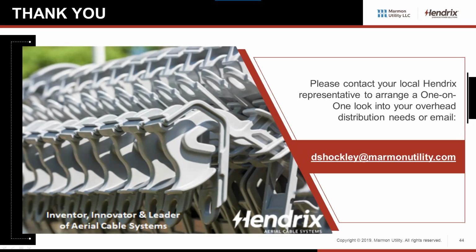Obviously a good chunk of our spacer cable is used in heavily treed areas. Lightning may hit an adjacent tree and some of that surge might transfer to the messenger. The downside to covered conductor is that pinholes made by lightning or other surges are difficult to find. Fortunately, it just doesn't happen very often.